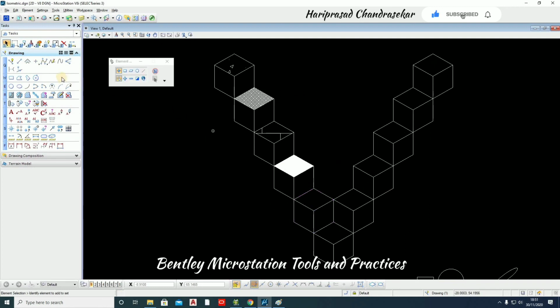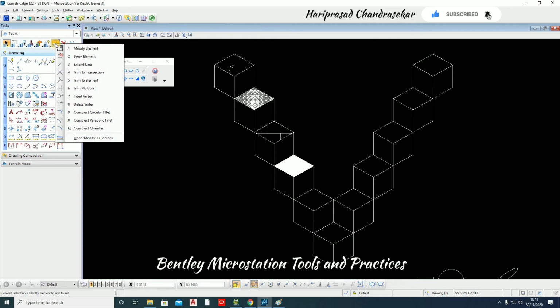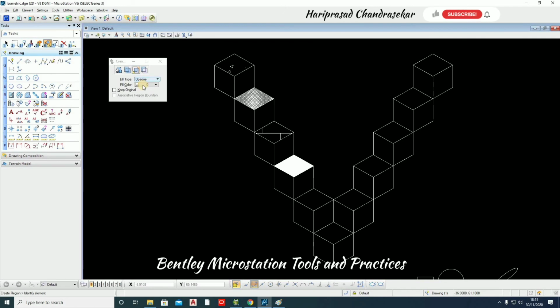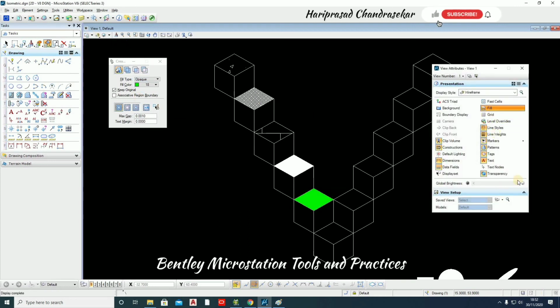But if you need a solid hatch, we have a region here. That region command creates a region, and you can go for a fill color of some green or something. And I'm just going for flood. It is deleting here, so you need to put keep original. I did it so many times and it was deleting the file. You need to click keep original. Why is the fill not appearing here? Because we also clicked fill off.